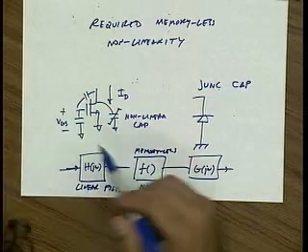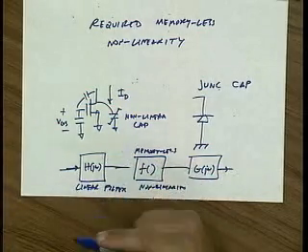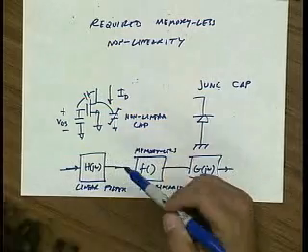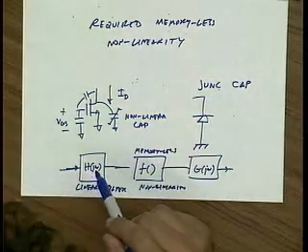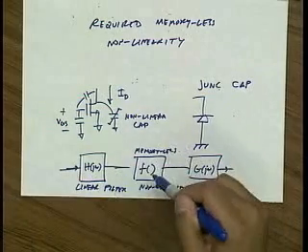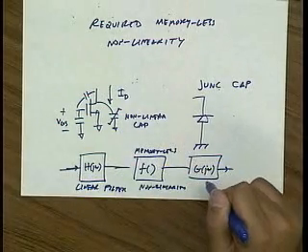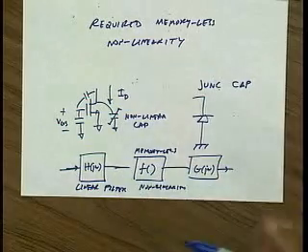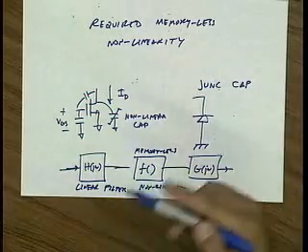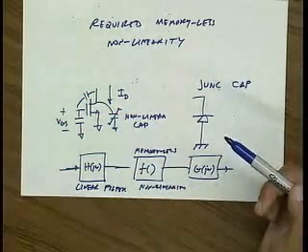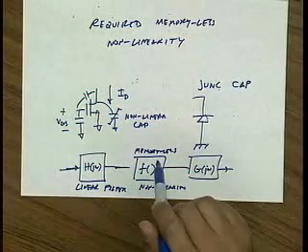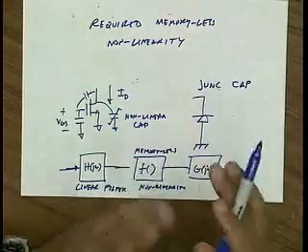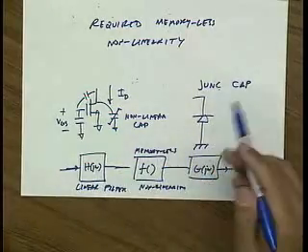So for instance, if you have a tuned amplifier, then you know which distortion products are going to get filtered and which ones are not. So if I come in with a two-tone, right, and then I apply it to some memoryless nonlinearity, the output will have third harmonic, right, fifth harmonic, second harmonic, all the intermodulation products. Well, the harmonics will get attenuated by this filter. The intermodulation terms, the ones that fall in band, into the pass band of the amplifier, will not. Let me just draw a picture for that.